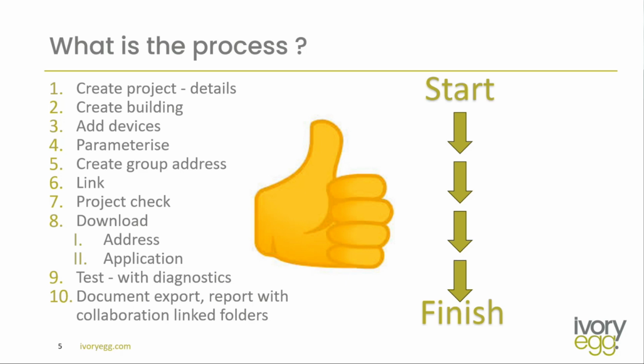It's a good idea, and I'm going to show you through the next demonstration, to do a project check. A project check is a quick assessment by ETS. It lets you know little warnings or errors to look out for. After we've done a successful project check, we need to download.